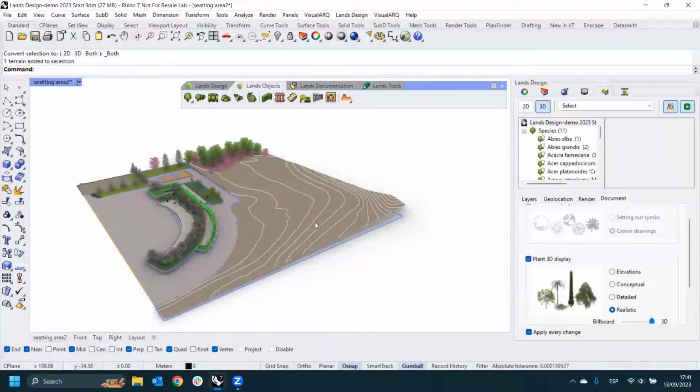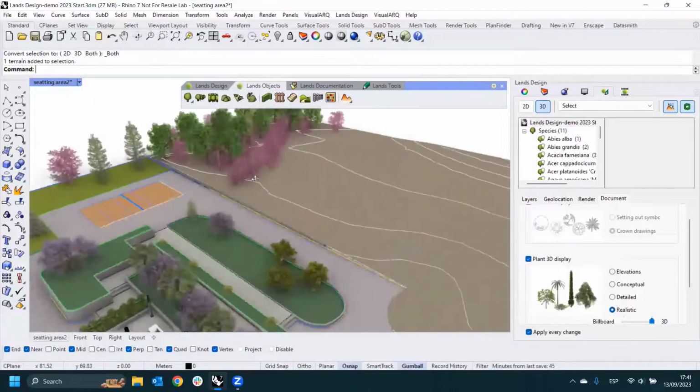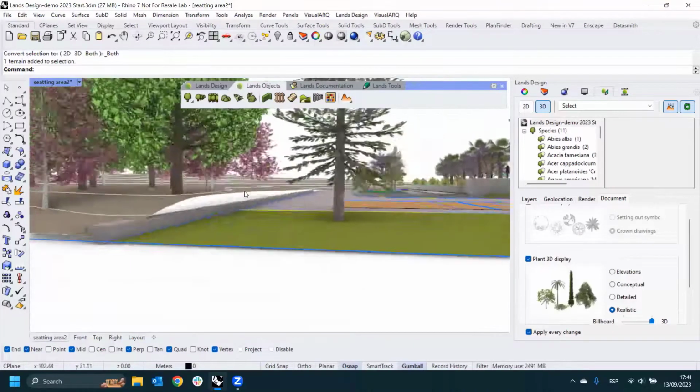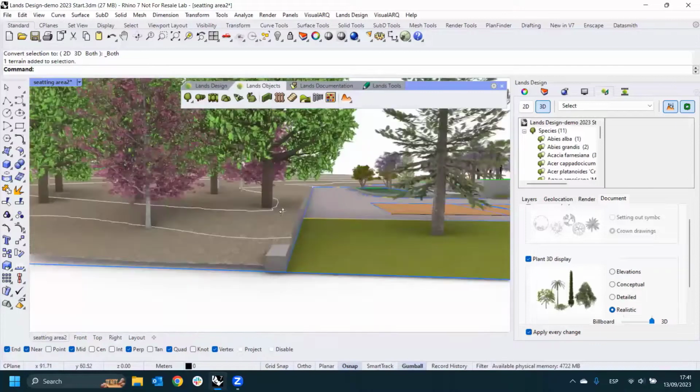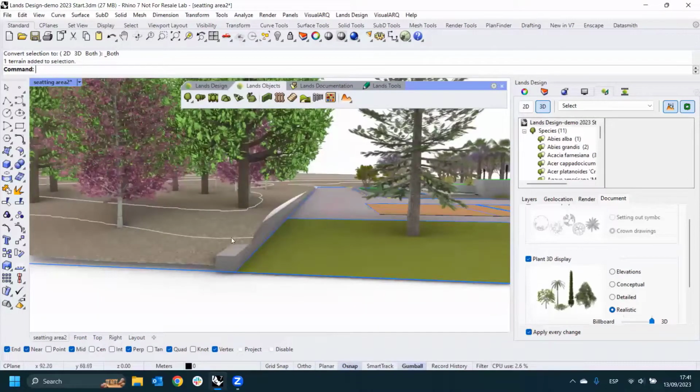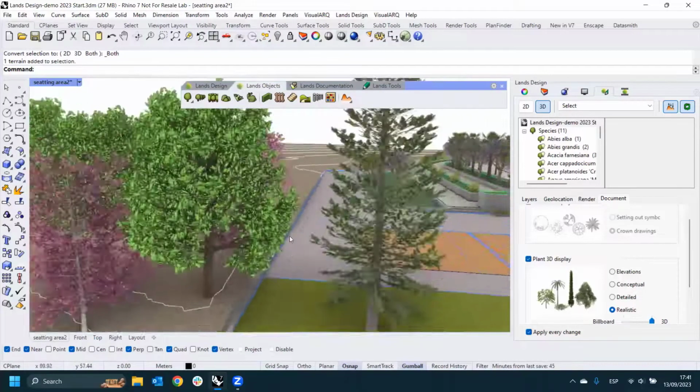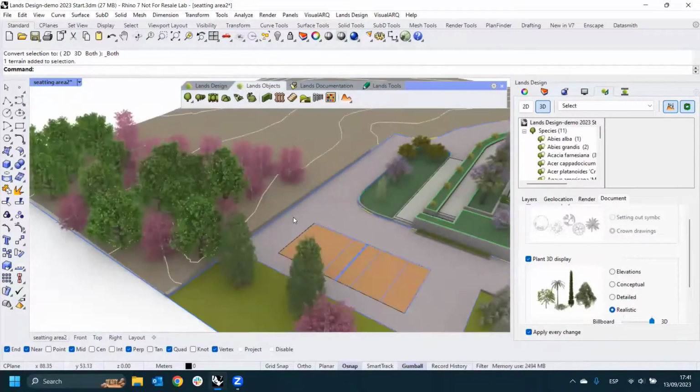Let's explore some other features that we can apply on the terrain. If we get close to here, we can see that there is some nasty gap here. We don't want this. And imagine that we just want to flatten this area in the intersection with this edge of the park. So there are different ways to achieve this. And one way is basically using one of the commands to do some operations on terrain, such as this one that will apply a cut and fill.